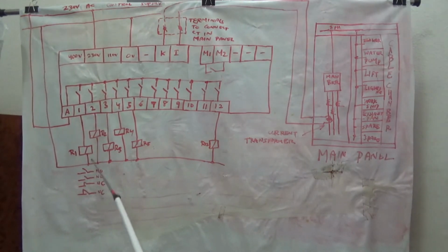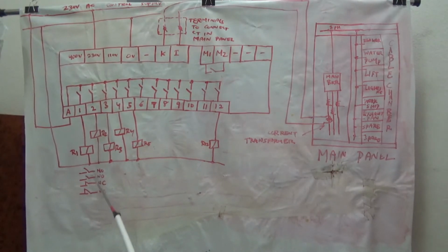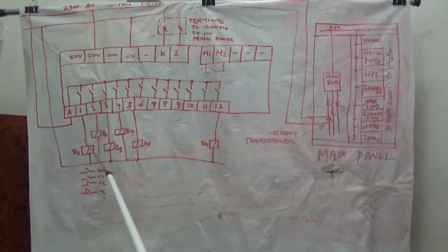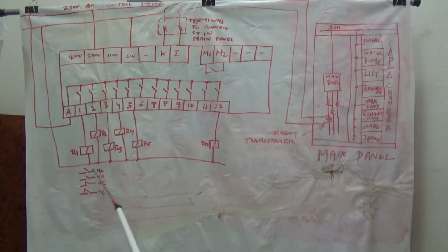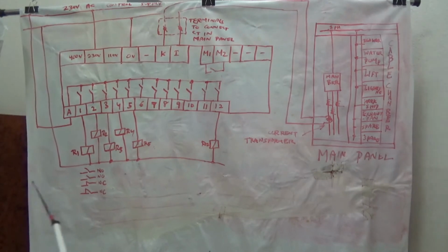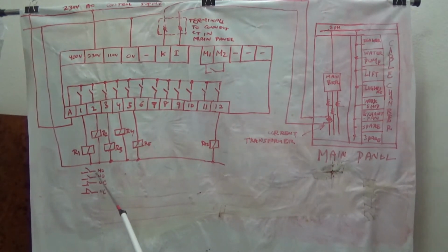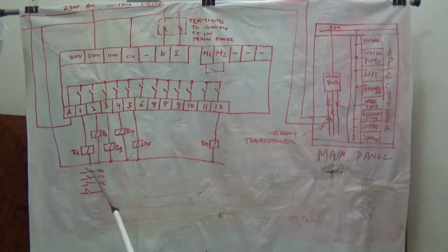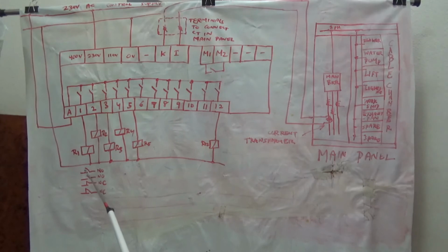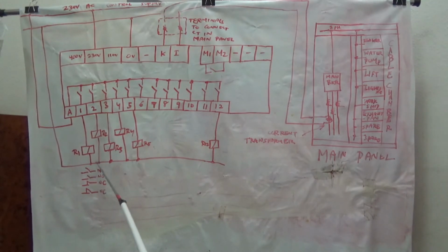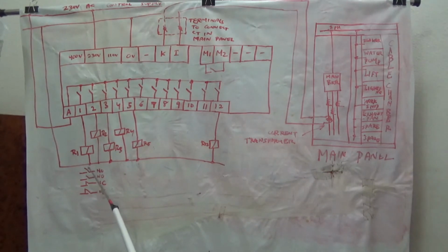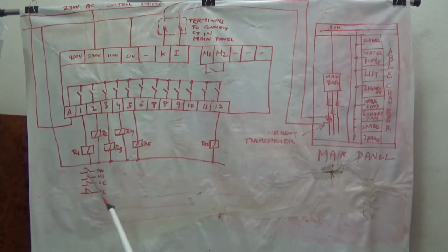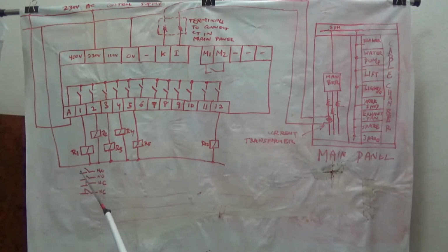It will have only small auxiliary contacts, and this contact will not be damaged, and this NO contact will energize the main big power contactors. This is called capacitor duty contactors, because there are many types of contactors: lighting contactor, motor switching contactor, but this is a special type, so this is called CDC or capacitor duty contactors.